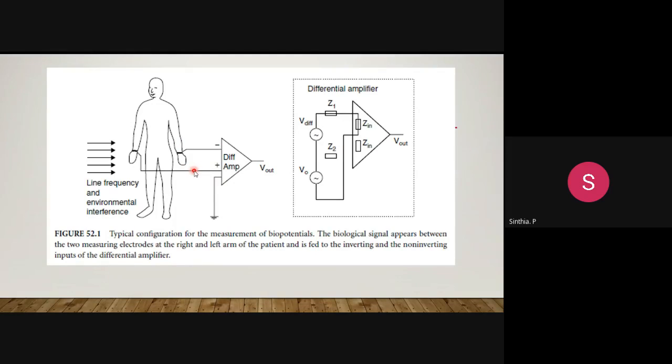The total resistance includes the resistance of the biological source and all the transition resistance between the signal source and the amplifier input. They might also cause thermal voltage noise, so this also has to be taken care of, and proper design specifications should be incorporated to avoid interference between the source and the amplifier system.